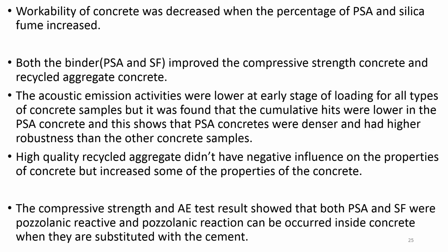Workability of concrete decreased when the percentage of PSA and silica fume increased. Both the binders PSA and SF improved the compressive strength of concrete and recycled aggregate concrete. The acoustic emission activities were lower at the early stage of loading for all types of concrete samples, but it was found that the cumulative hits were lower in the PSA concrete, and this shows that PSA concrete was denser and had higher robustness than the other concrete samples.